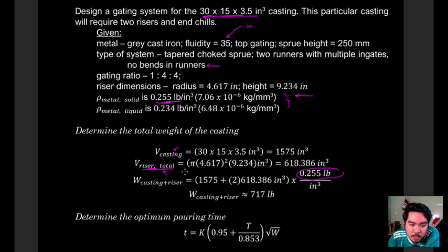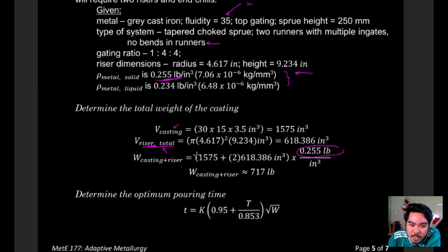Pero this is good enough na, no? So, again, for casting design kasi it's not necessarily an exact science, no? Posibleng in most cases medyo inexact lang siya. We are assuming certain values, and those assumptions are educated assumptions, no, based on the knowledge we have. So in this case, kahit hindi natin i-account yung gating system, enough na to na